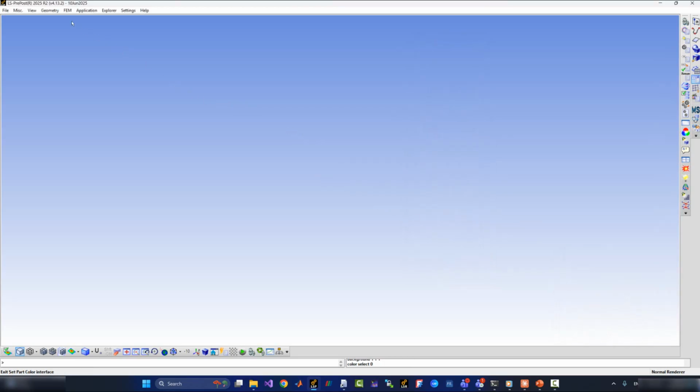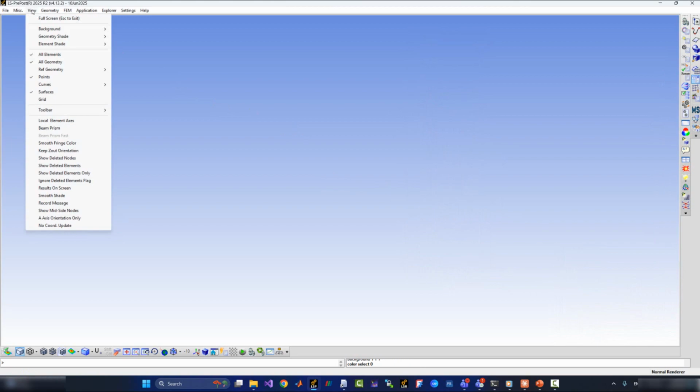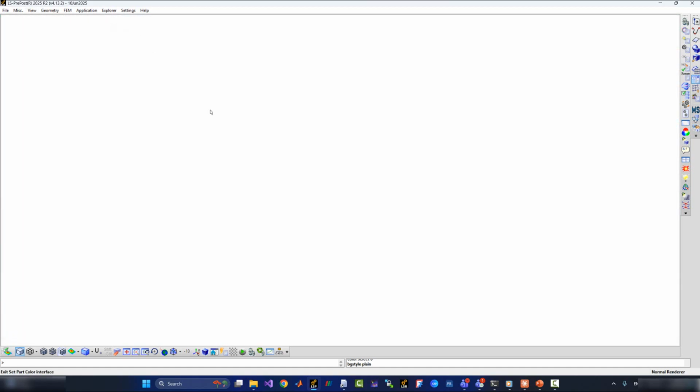What happens is if you go to the View menu, which also is the obvious choice if you are trying to mess with the viewport and the color definitions, you may find this option here, the background option. The background by default is a bicolor fade configuration. So the idea is we have a bottom color which is slightly lighter, if you may be noticing, and gradually it fades to a different color as we go from bottom to top of the screen. To activate the single color definition that we assigned, we have to activate this plain option. And lo and behold, this is our plain white background.